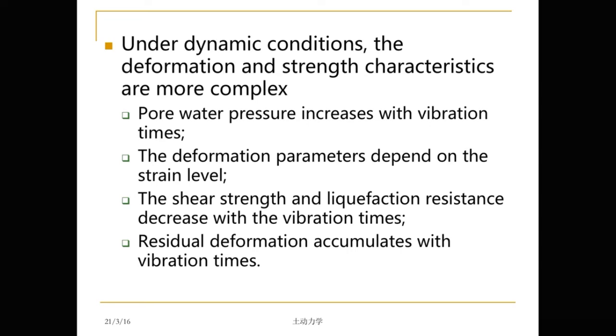And if the total stress is constant at this moment, when the pore water pressure increases, it will cause the decrease of the effective stress. And the effective stress can also be used to evaluate the stress status during the earthquake.